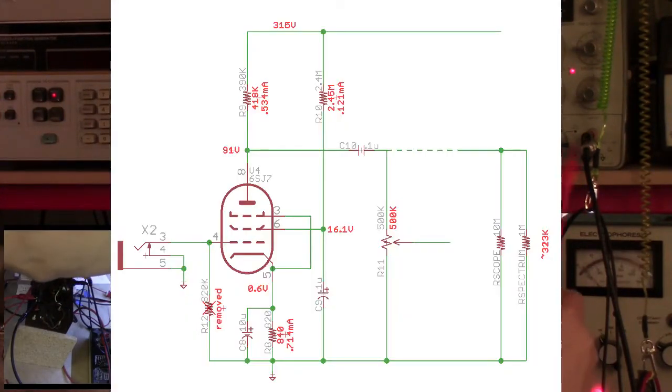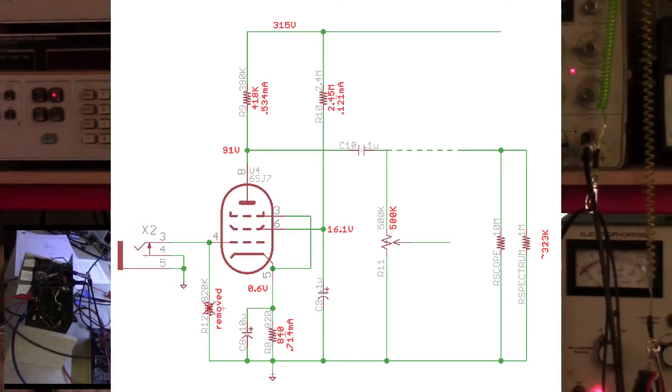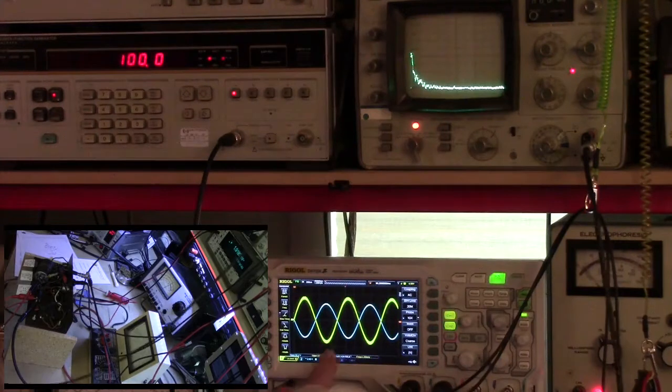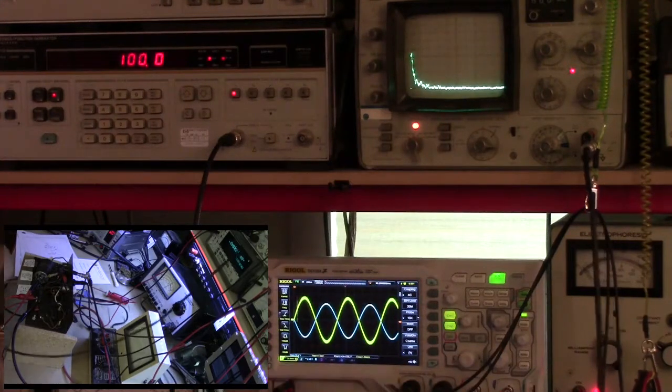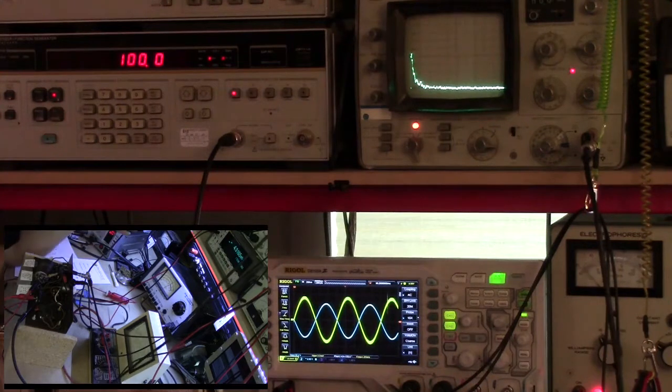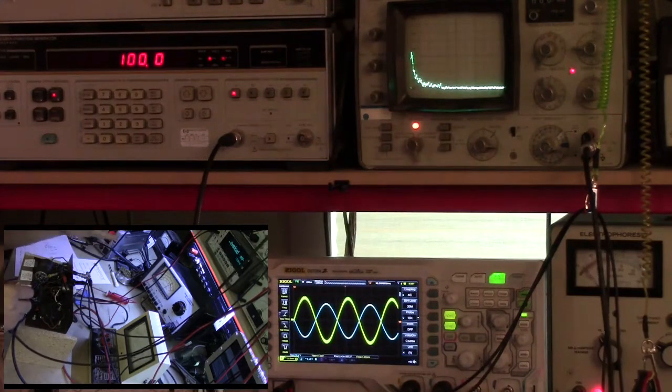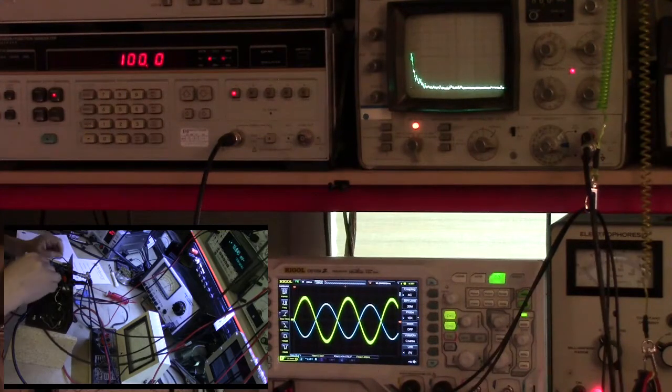So when I connect up my probe voltages here, what you're going to see is the blue wave, the output waveform, is going to go down a little bit because we're loading down the circuit more. We've put an extra 1 megohm resistor across that 500K pot, which drops it down. So we're going to get a little bit of reduction in the voltage, but spectrally, we're going to get to see what the spectral content of the output voltage is for